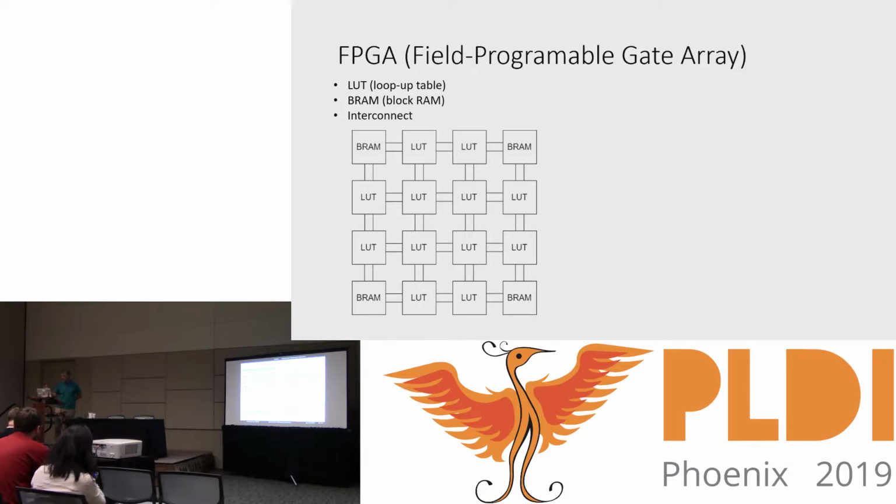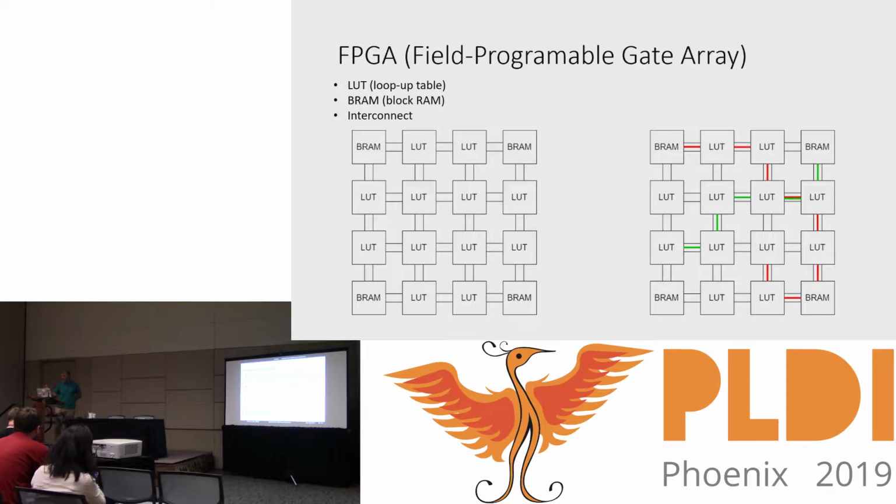And how it's implemented is a grid of lookup tables, which can be programmed to express functions as an input to output mapping. And then some interconnect, which when we wire it together, basically computes the tensor graph process. But this is performed at bit level. But you can view it as a data flow through nodes of functions.